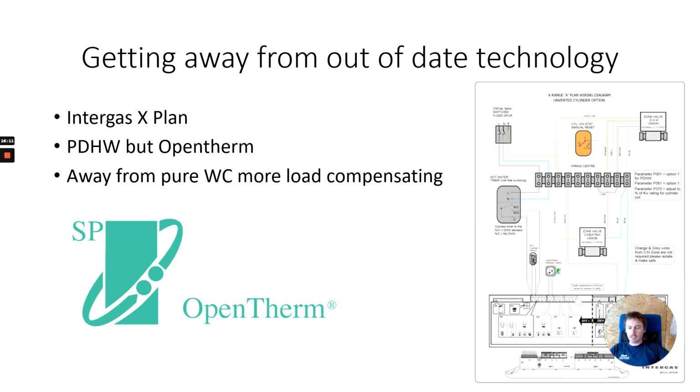First of all, you need the boiler to have an OpenTherm capability, and you need it to be wired the correct way so the OpenTherm is controlling the boiler. The thermostat starts to see the rate of change in temperature in the room, and that starts to modulate the boiler, as opposed to the boiler just getting a 230 switch live and trying to control itself on flow and return temperatures.